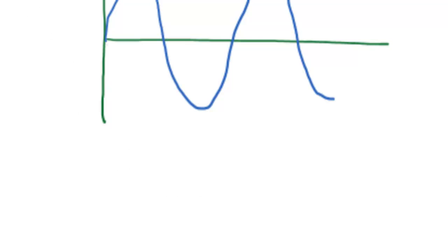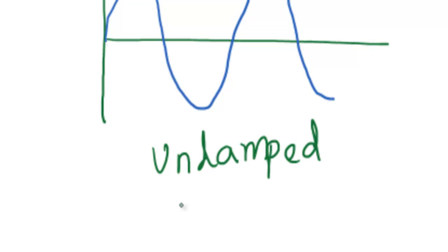Here, first assume no damping in the system, that is, an undamped system. Undamped means resistance is 0, so you will have only inductance and capacitor. In that circuit, once the switch is turned on, the current flowing through the switch, thyristor or load will be an exactly sinusoidal waveform, that is, an undamped sinusoidal waveform.